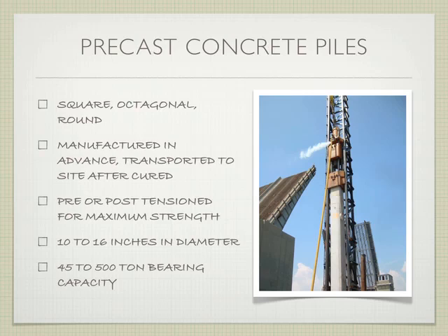Yes, Casey? No, because it's really difficult to attach those two pieces, and they would lose their bearing capacity through that attachment point, right? And so they need to cast those in one monolithic piece for them to work correctly, right? So if you needed a pile that was too long, you'd have to use steel, right? And so in a precast facility, the casting beds tend to be about 800 feet long. So theoretically, you could make an 800-foot pile.